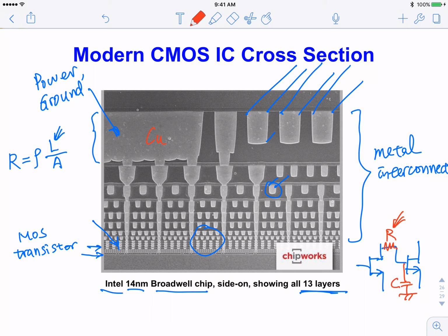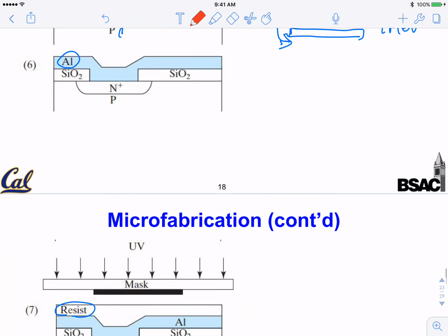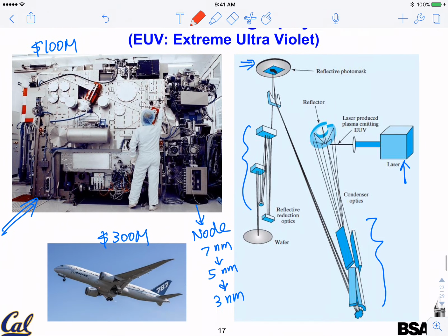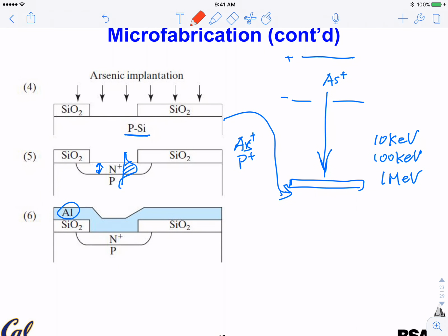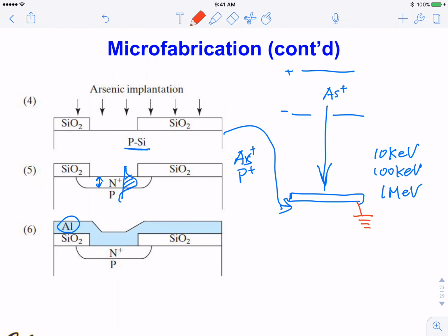Any other question? Yep. In the ion implantation process, the positive ion is shot at the wafer. Is the wafer still charge neutral? That's a very good question. Yes. So you imagine you keep shooting ions in there. So this needs to be grounded. This machine, called an implanter, is itself a circuit, and you need to have a closed loop. Otherwise, you build up so much charge, your next ion will deflect, and that's a problem. So you need to conduct it usually through the substrate.